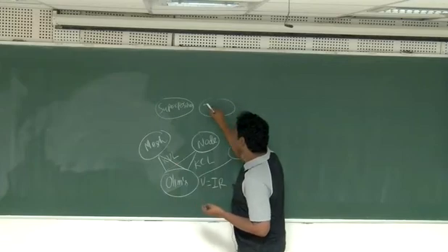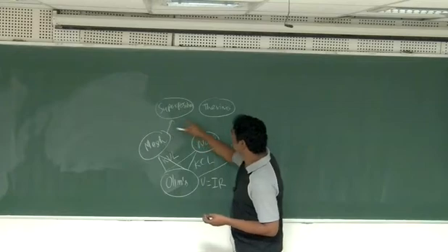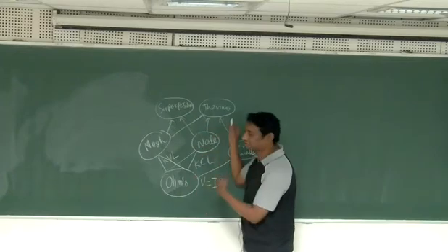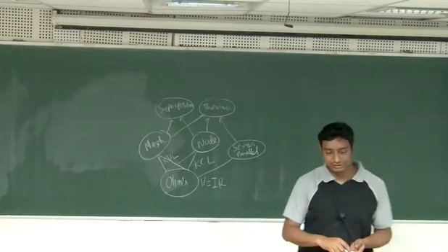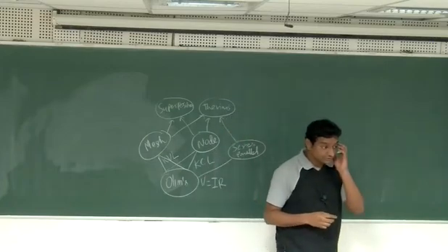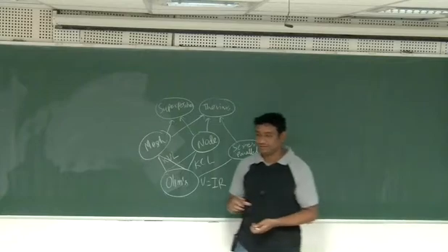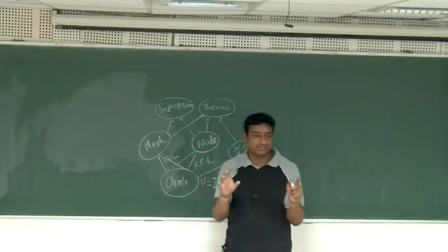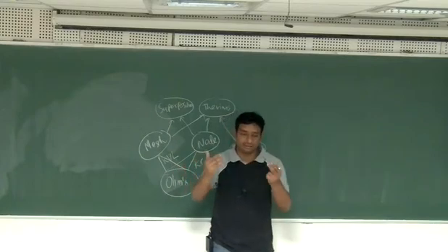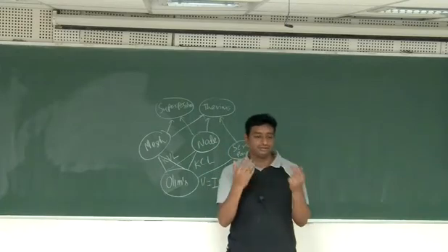And then we also saw Thevenin's theorem. All of these are kind of used for going up. So in Thevenin's theorem, what are you trying to do? It is more like finding an equivalent. Given 2 points in the network, if there is a load resistance between the 2 points, you just take it out, and the rest of the network may have 10 resistances, 3 voltage sources, or whatever.